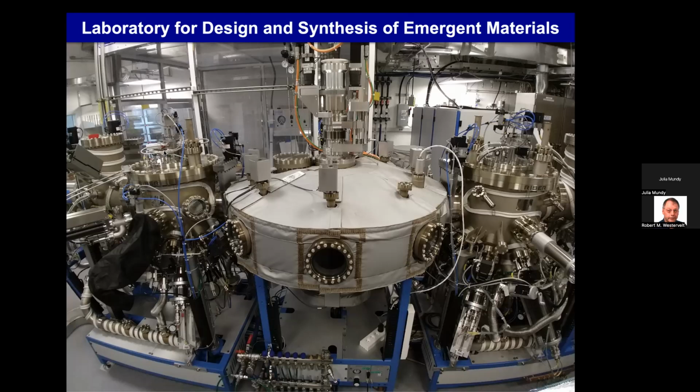So our experiments happen in what we call ultra high vacuum. So we evacuate almost all of the air from inside the chamber. This room is 760 torr. We go down to 10 to the minus 9 torr. So there's 10 to the 12, one atom in 10 to the 12 is remaining inside of our chamber when we do our experiment. And so if we want to get our sample in or out, because we want to make some measurements, of course, we don't want to vent the entire chamber and then wait days for it to pump back down. So we have this vacuum can in here, and on the back, we have a small load lock,